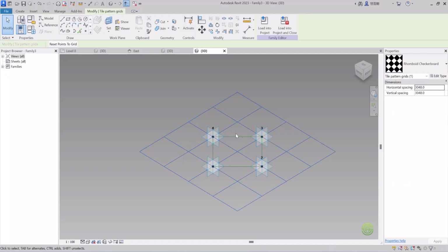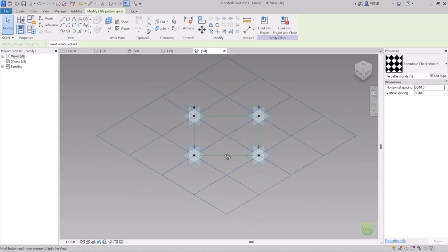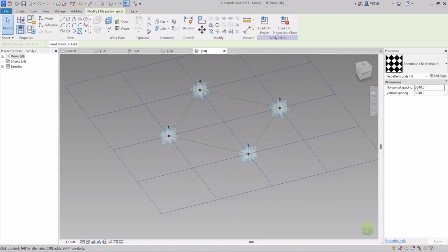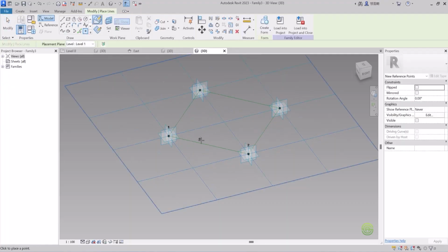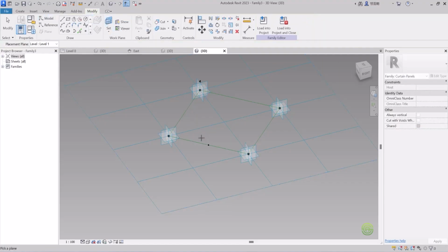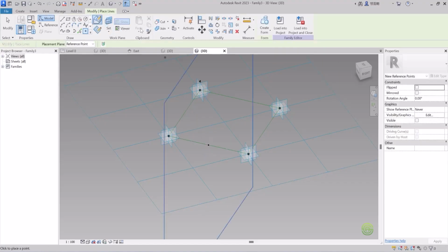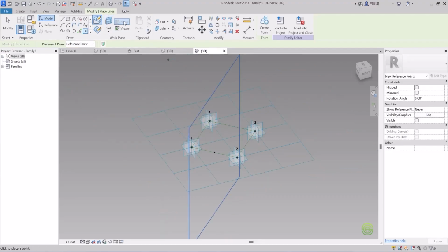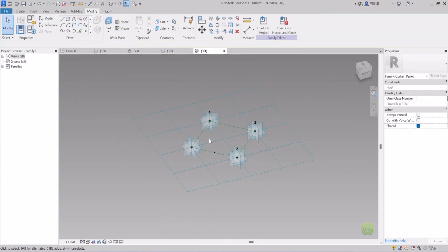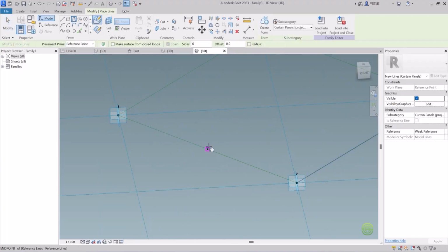Now the thing is we have to use the sweep concept. So to make a thickness to this, just click on point element and just place it in the path and set a work plane to this and place it here and just click on show. We can view this work plane and now let's draw a hexagon like this. So let the hexagon be like this.